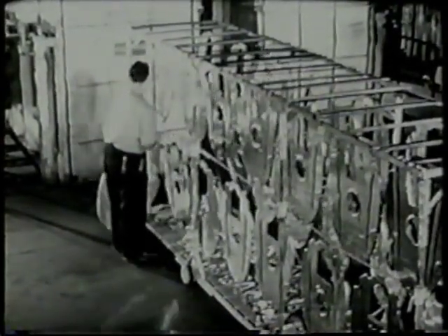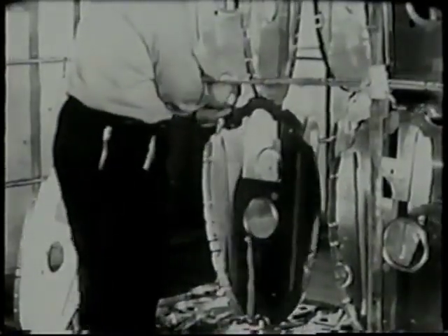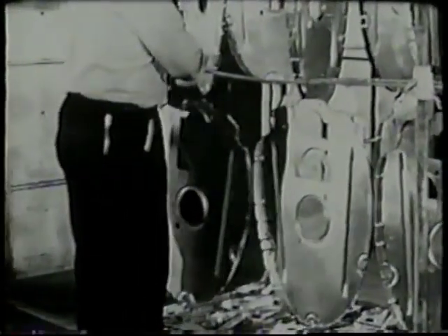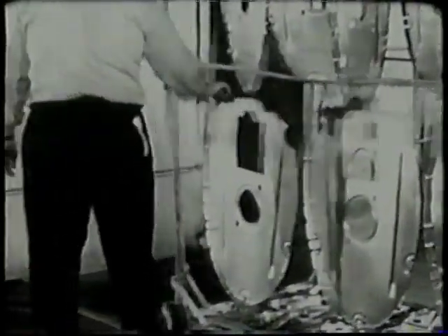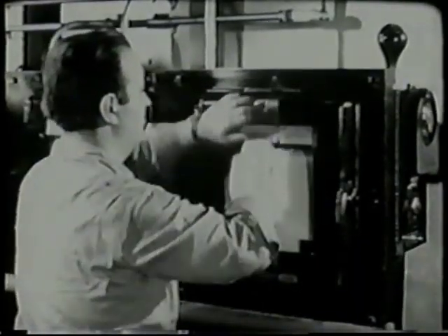Parts to be heat treated must be properly racked to minimize their tendency to sag at elevated temperatures and to reduce warpage during the quench. Sufficient space should be allowed between parts to promote free circulation of the heating medium and later of the quenching water. The loaded rack is now ready to be placed in the furnace.